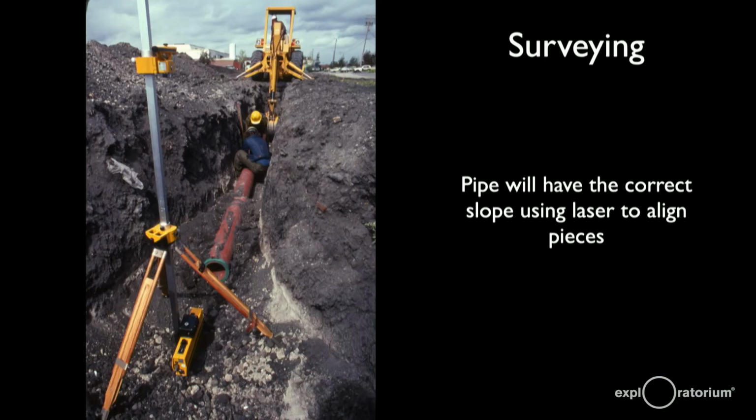Or if you're in farming, you know how to make a field perfectly tilted as well, because otherwise irrigation doesn't work. You have to have the field tilted just a little bit so the water runs down. For instance, here, they're installing a pipe, and they have a laser down at the lower left-hand side of that pipe, and it's shining up along the pipe, and they can lay the pipe so that it's straight right along the laser beam and that it's tilted properly. Sewage pipes, for instance, have to be tilted just at the right angle, otherwise the sewage won't run down them.